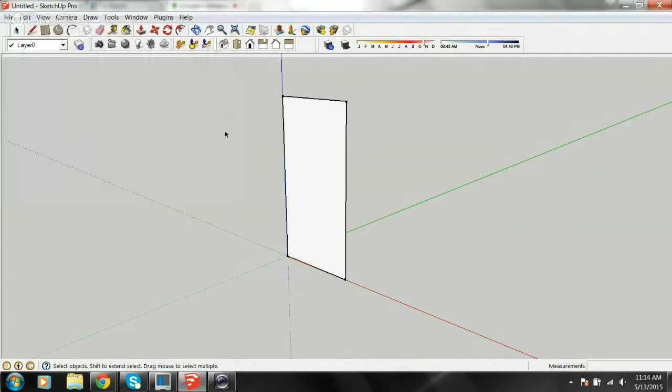Now, the first thing that I like to explain to people when they're new to SketchUp, or even some that have a little bit of experience, is that if you've never worked in groups, you've got to start working with groups. In this particular model, what you're really looking at is probably a masonry group, like the main facade, a cornice group for that top parapet cornice that we're going to work with, and then maybe a windows group and maybe a doors group and maybe a lights group. If you set everything up as groups, then you can individually edit them without affecting other pieces.